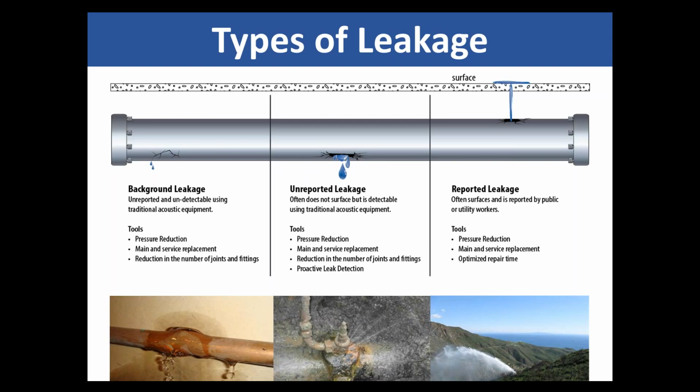So you have repair records. This year, by doing leak detection, we found 50 service connection leaks and a couple of main leaks, for example. So that's the volume we can then attribute to unreported leakage. The ones that are reported that find you, that's the volume that goes to the right. The ones that we find proactively, we categorize as unreported leakage. Also here, pressure management is a tool, and again, obviously, how long does it take to repair it, right? And that's a capacity question.